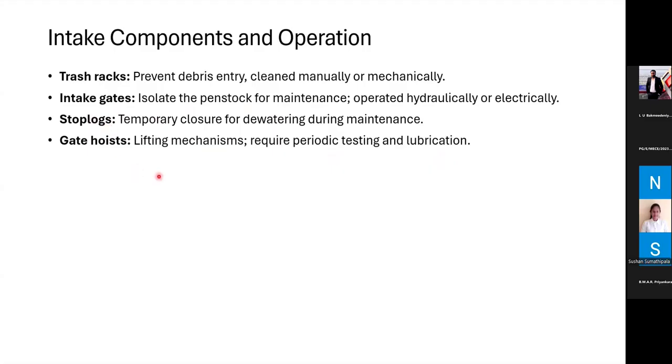As I explained previously, dewatering the tunnel doesn't happen that regularly. That means these assets in the intake are not used much, and might just sit there waiting for maintenance that comes after about 10 or 15 years. At that particular moment, we have to make sure these elements work, so they have to be maintained throughout that time.